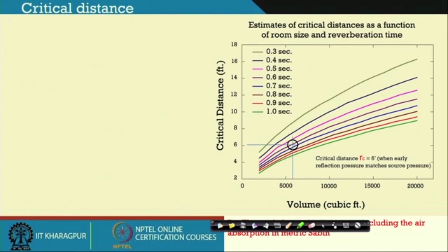You see this graph. Here you see that with a set of reverberation times, a number of curves have been drawn for different volumes in cubic feet.